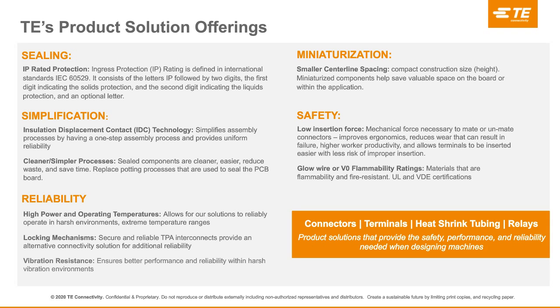And again, with safety, we're looking at two areas. The first is obviously with your operators. We want to make sure that there's a low insertion force and decent pads on the end of the plastic housings that you're inserting, to make sure that we're not causing any ergonomic issues and problems that can ultimately lead to poor interconnect if they're not being pushed on fully.